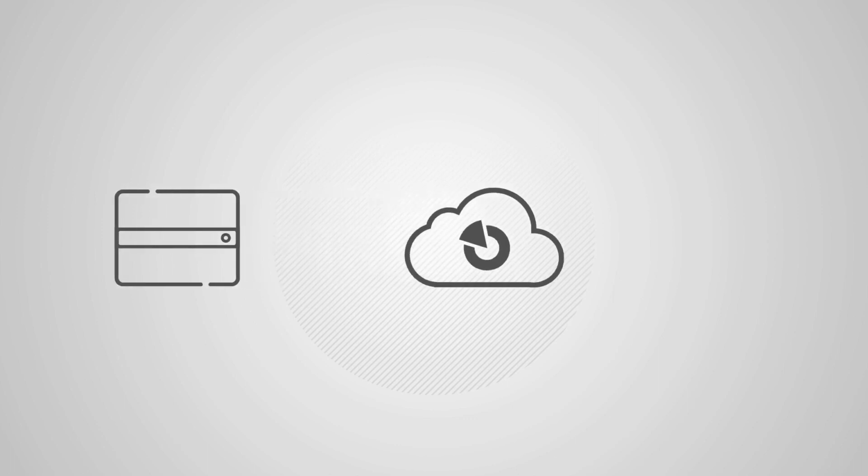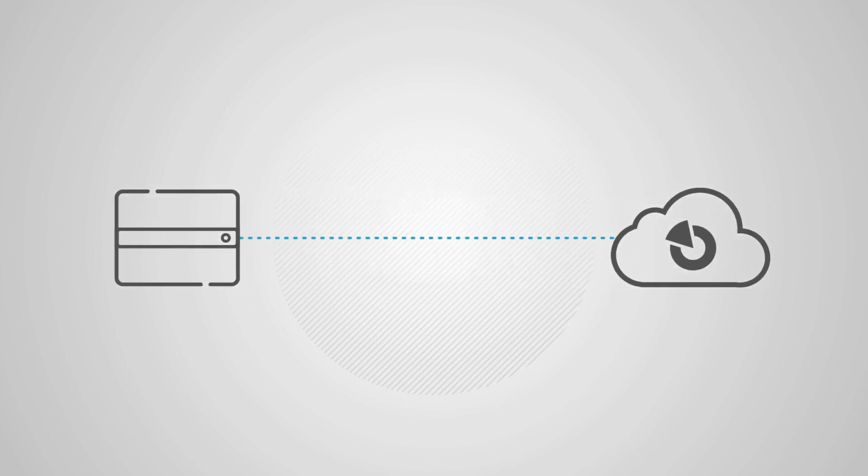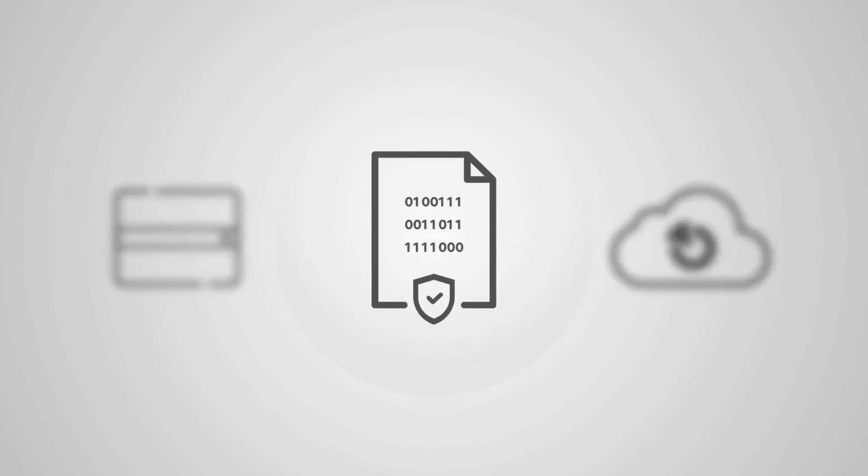Communication for control and event reports between the control panel and the cloud runs through two different channels. Channel 1 is primarily data communication using LAN or GPRS. In case of any data communication issues, it is backed up by Jablo SMS. The communication runs on Jablo IP encrypted proprietary protocol. This channel sends the important information: ARC events, arm, disarm, alarm, low battery.